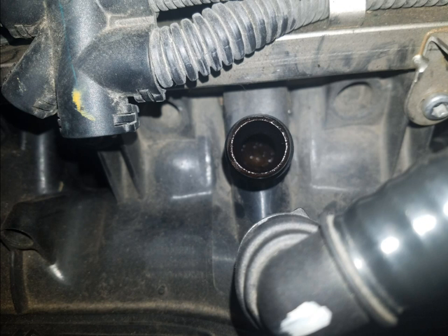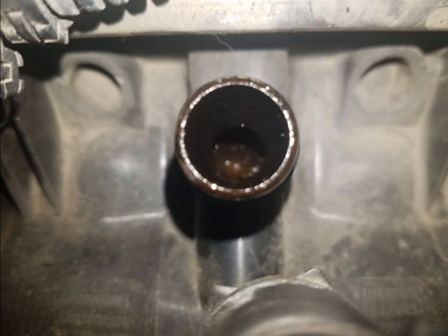So the repair for this vehicle will be to replace the intake manifold assembly and replace the valve cover assembly. If we replace only the valve cover, we've replaced just a symptom, and it's going to return, and we'll be continually replacing valve covers on these engines. The intake manifold has an updated design valve that solves this issue permanently.